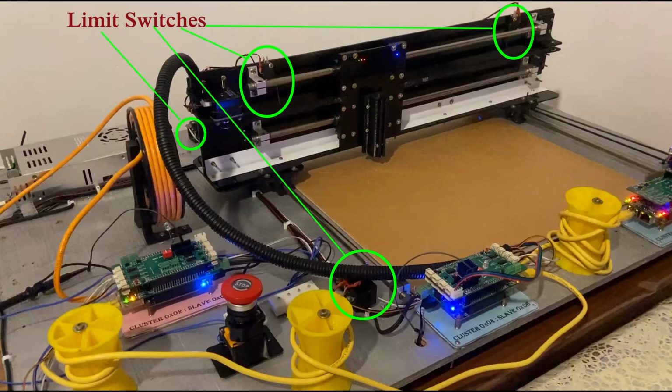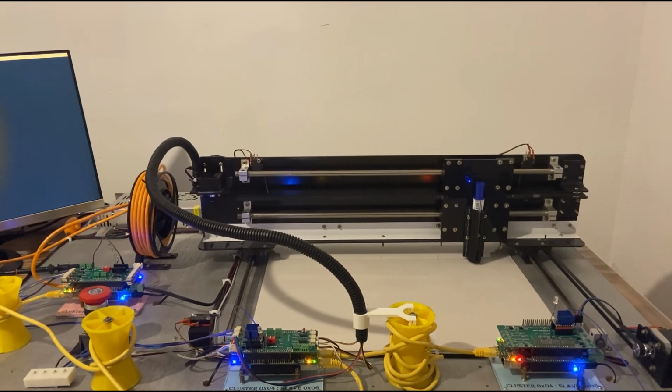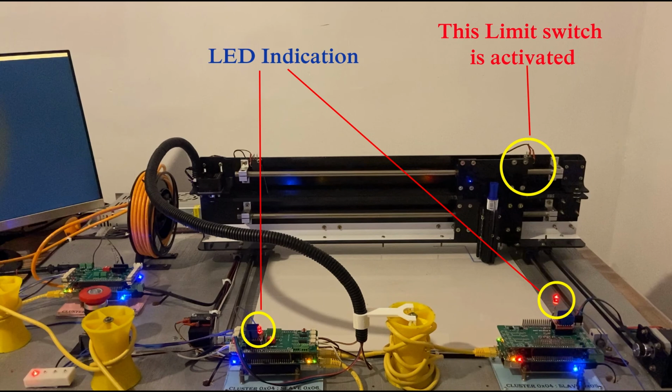In the second scenario, we are going to demonstrate a situation where limit switches get triggered. We have configured all these limit switches in the same cluster. In such a scenario, the emergency should be enabled only for the relevant cluster. Here you can see the red LEDs are turned on in slave 5 and 6, which are in the same cluster. As slave 1 is in another cluster, that emergency is not applicable for it.